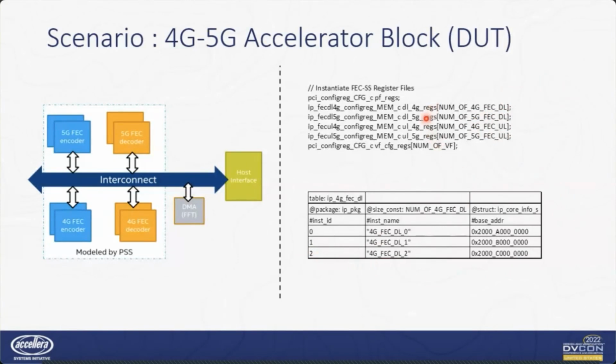Then the exec body can automatically write into instance 2 of this register component and then the associated register within that component. So this is how we have basically used the randomization of Perspec along with the HSI sequences we have written to develop our portable driver.